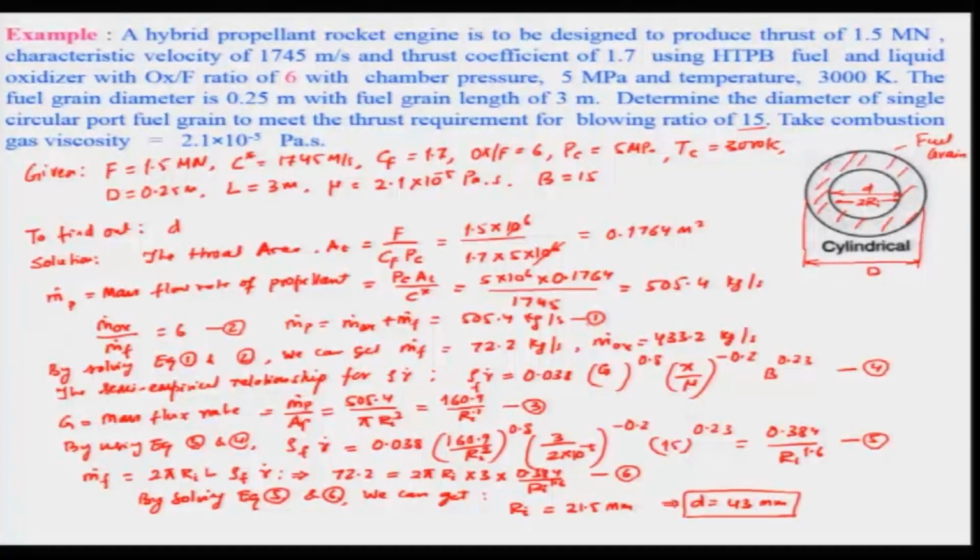So, here we have learned how we can utilize the semi empirical relationship for designing the port area in the case of a hybrid rocket propellant engine. And with this we will stop over here.